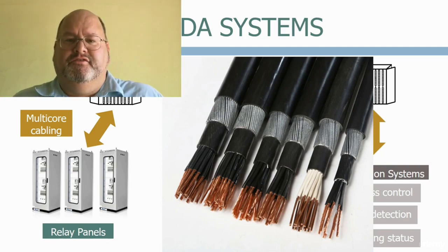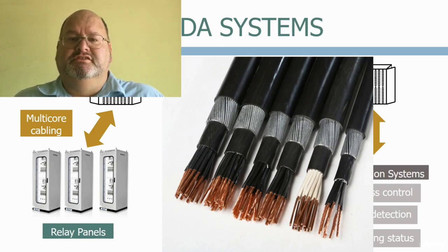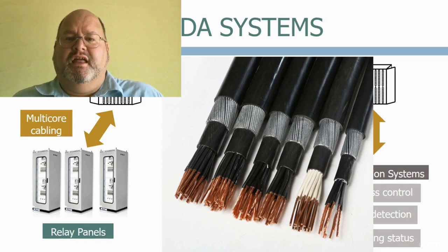As we've seen in the first protection course, we provide independent Main 1, Main 2 and backup protection systems for most transmission circuits, all fed from their own DC supplies and systems. This level of redundancy is considered essential to maintain the security of the substation, and it's unlikely that hardwired systems will ever be fully replaced with a LAN and RTU-based option.